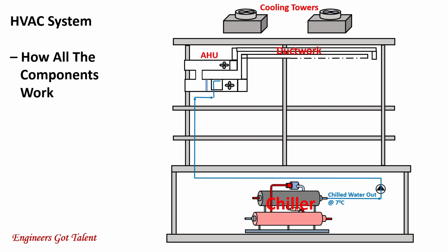At the AHU, the ambient fresh air, which is now filtered, and recirculated air from the rooms is cooled by the chilled water. The chilled water temperature increases and goes back to the chiller at the evaporator as warm water at 15 degrees Celsius. The warm water goes inside the evaporator tubes and its heat is absorbed by the refrigerant. The warm water and refrigerant don't mix inside the evaporator vessel. The warm water cools down and then exits the evaporator as chilled water. The heat from the warm water is absorbed and carried by the refrigerant at the evaporator.